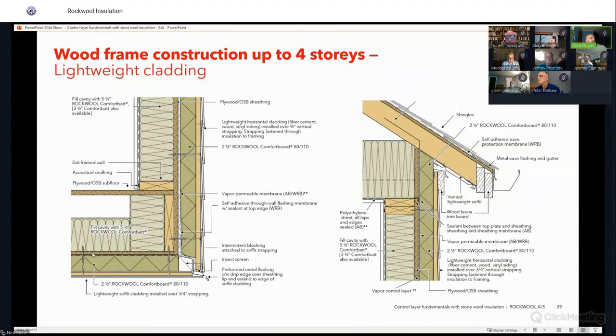I'm not sure how many of these areas you get into, but cantilever overhangs, certainly in my area, are pretty common. Again, continuity: you're bringing a thermal plane down. We just want to make sure we have our connection point moving on to the other side. Same thing with the air barrier. As the air barrier comes down, we really want to make sure that it wraps down and around, so that way we don't miss an area here, bringing that continuity around the corner.